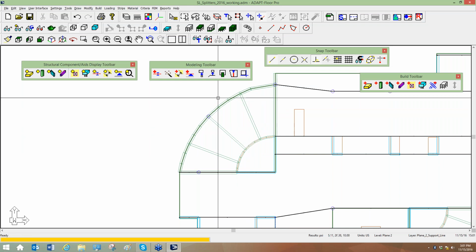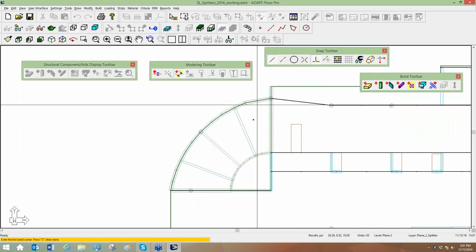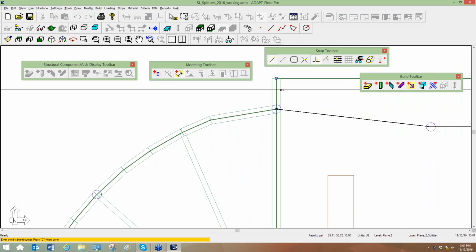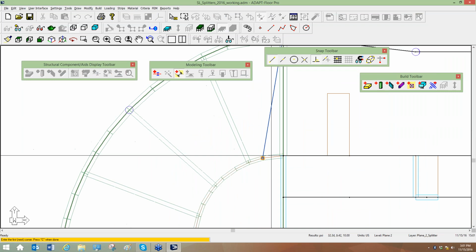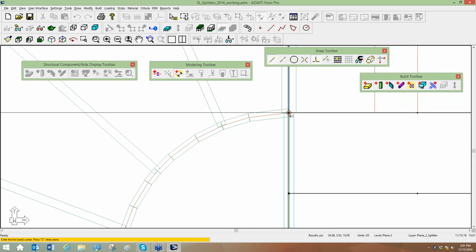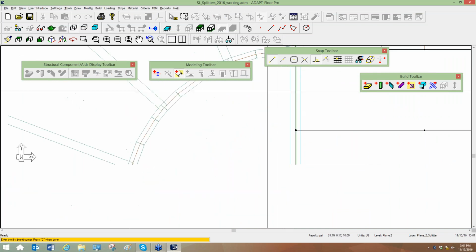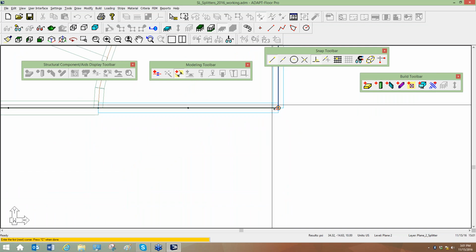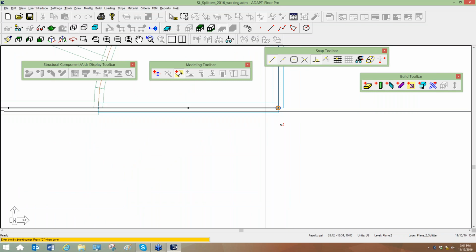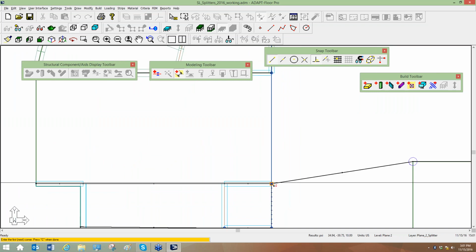Now I'm going a step further and adding a splitter along that zone. So I'm going to take a splitter and go all the way to the top corner of the slab, and I'll snap down to this line, this line. There's a corner of a support line which stops at the corner of the slab, and we'll take this all the way down to there.